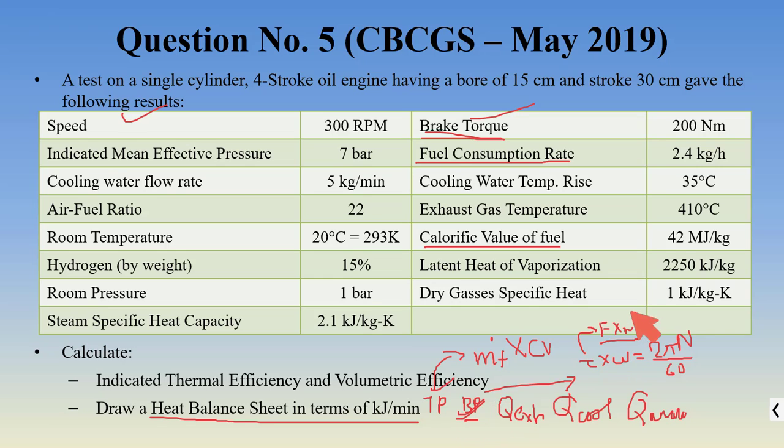So we can substitute these values and get brake power. Here, rather than giving force, they have directly given us the braking torque, so we can directly substitute that value over here and find brake power.